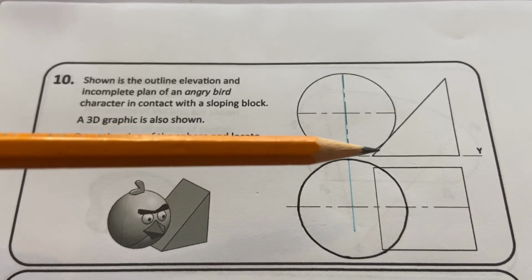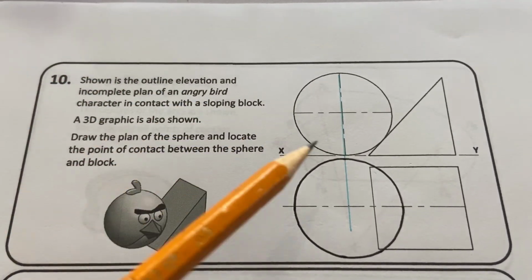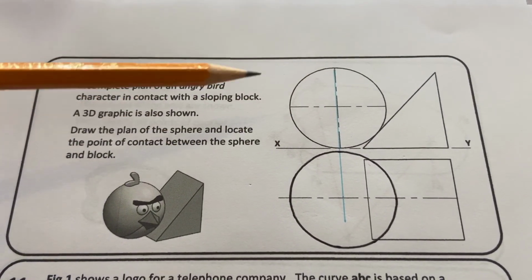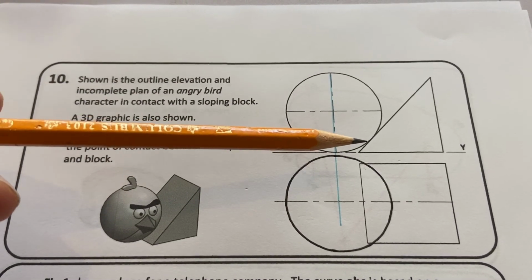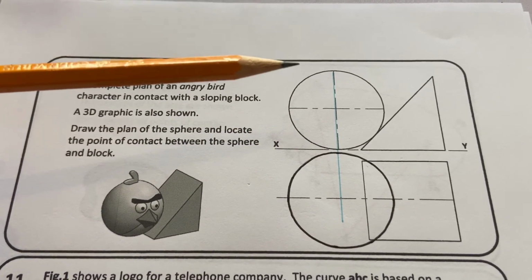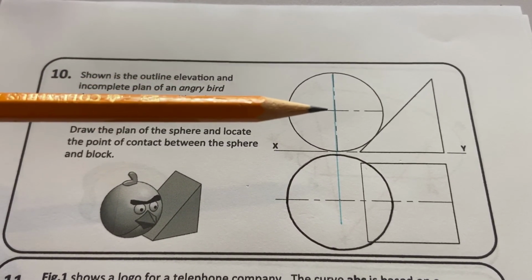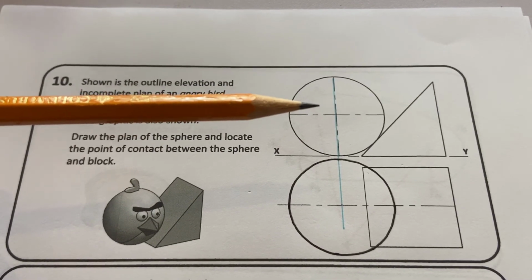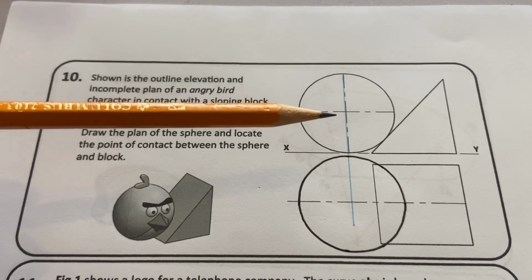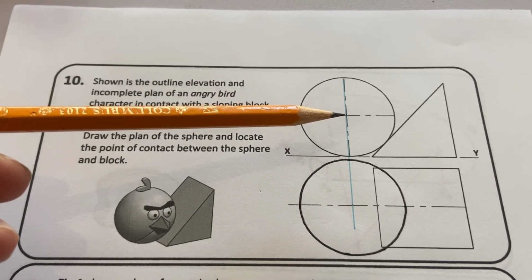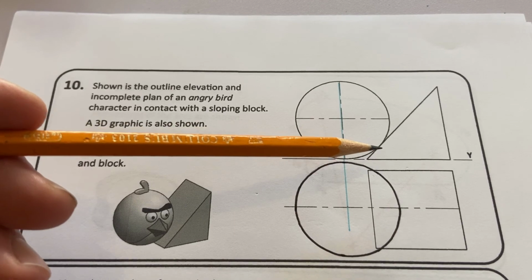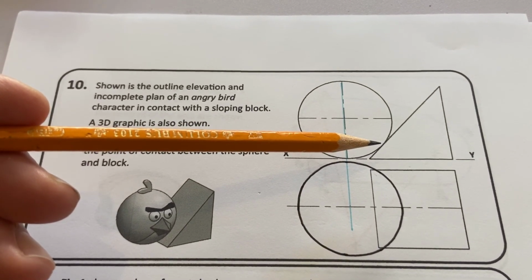So the next thing we want to do is locate the point of contact. Now we can see that the point of contact is going to be in this region here. Now we have a circle and we have this block, and the side of the block is tangential to the edge of the circle. Once the concept of tangents is mentioned, an angle of 90 degrees should come into mind. So in order to get the point of contact, we draw a line from the center of the circle at 90 degrees to the tangent, or the line here on the block. And that will give us the point of contact here.